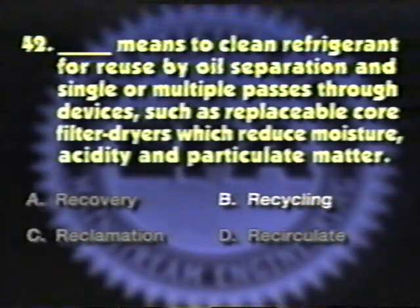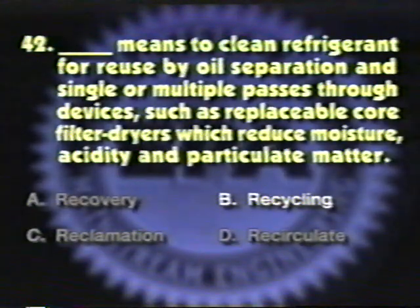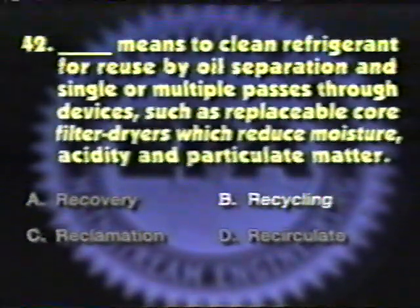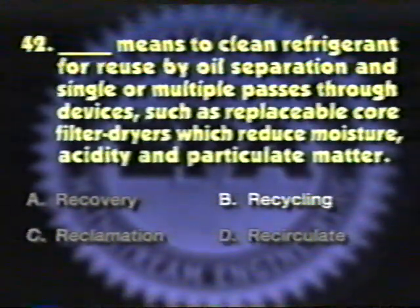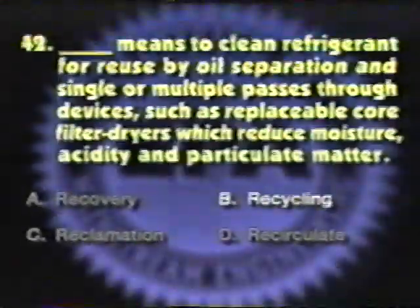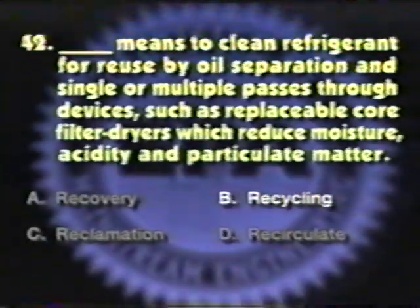The correct answer is B. The definition of recycling is to extract refrigerant from an appliance and to clean refrigerant for reuse without meeting all of the requirements for reclamation. In general, recycled refrigerant is refrigerant that is cleaned using oil separation and single or multiple passes through devices such as replaceable core filter dryers, which reduce moisture, acidity, and particulate matter.